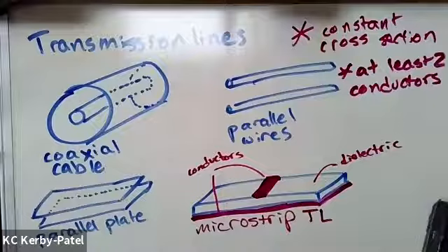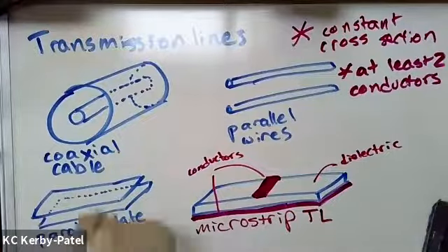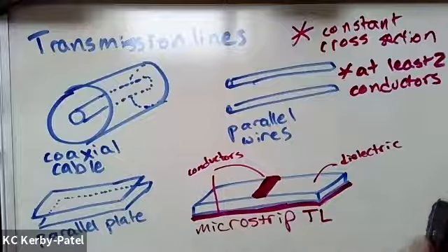Transmission lines describe not just the important effects that happen when the wires in your circuit are long compared to a wavelength, but they also describe things like how does crosstalk happen on integrated circuits and other sorts of things where you have high frequency transients that are really close to each other.